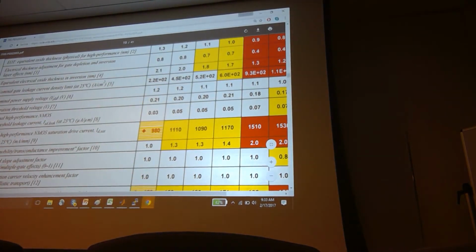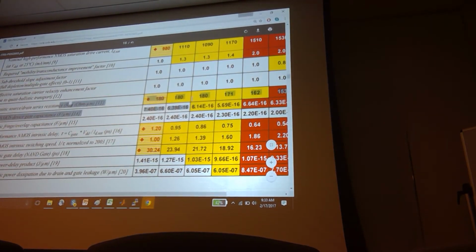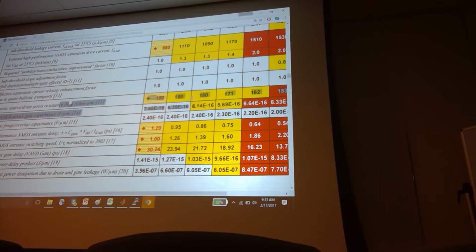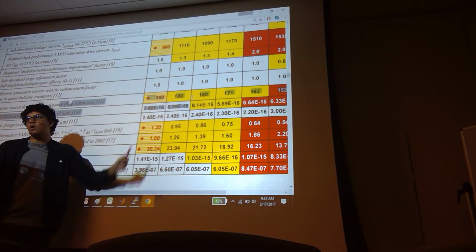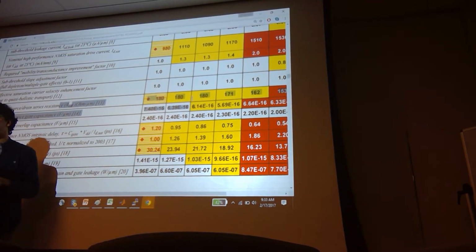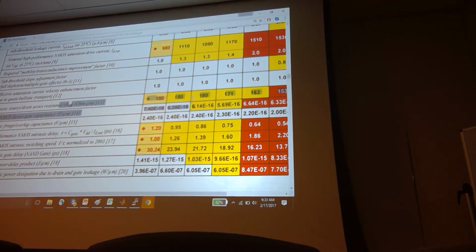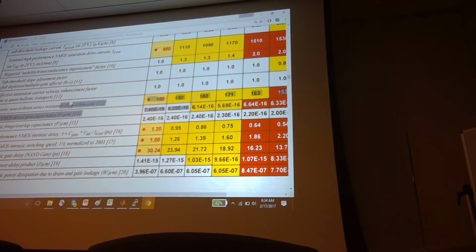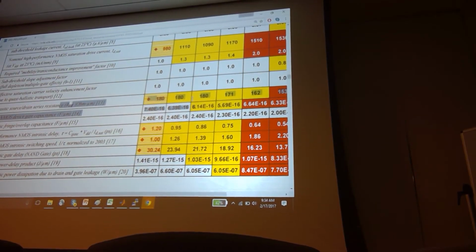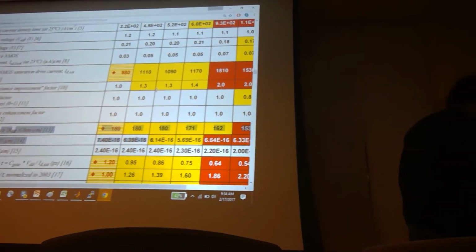You don't have to worry too much about these parameters. But you do have to worry about this, okay? Parasitic source drain resistance. So it has to be within this limit. This will help you to choose what length of the source drain regions you need and what doping you have to make it. And your threshold voltages that I've given earlier will help you decide the doping for your channel. So yeah, there are so many rules. Which one should we follow? No, that's why I said don't follow all of them. Think about what all you need. Okay, I'll move on to the transistor part now.